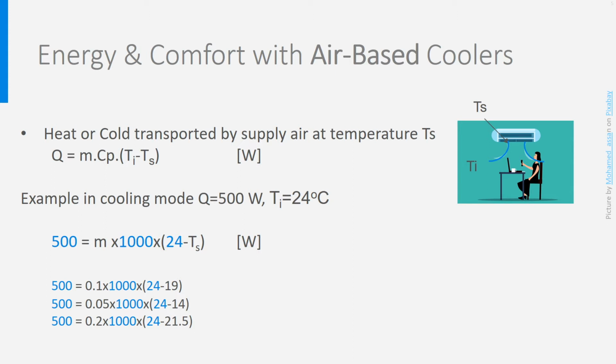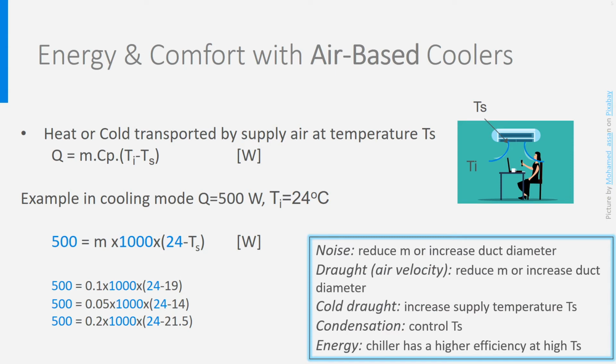In practice, as was seen in earlier lectures, this freedom is limited by restrictions on the mass flow rate. A higher mass flow rate in the supply duct means high velocities and therefore noise, unless a larger duct is placed. Another limitation is the supply temperature Ts. If it is very cold, people will feel annoying cold draft.